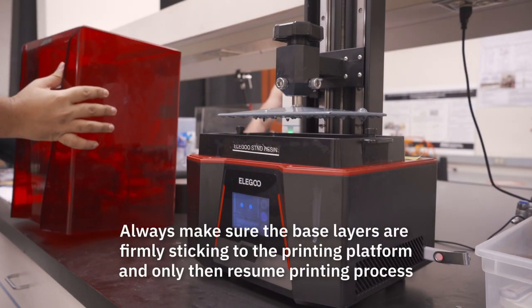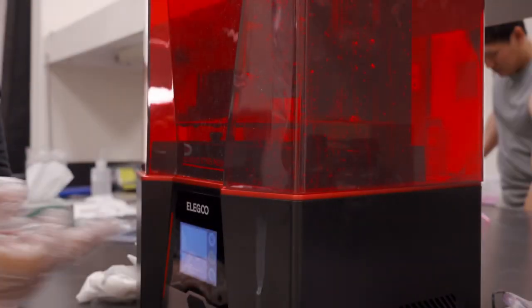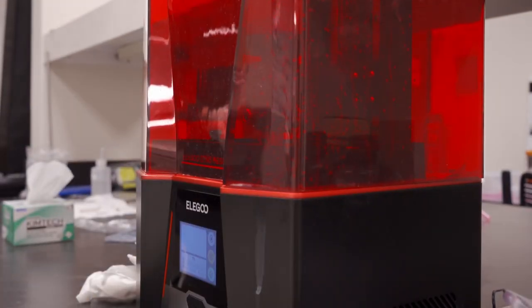We are now pausing the printing process to confirm the adhesion of the base layer as previously mentioned. It is challenging due to resin droplets, but looking closely, the two circles that form the base of the rook pieces are visible. Resume the printing process, which, depending on the size of the print, may take from minutes to hours overnight.